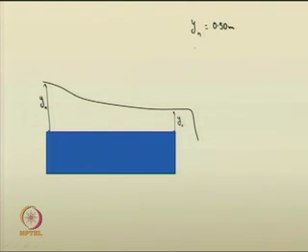Critical depth, you had evaluated the discharge; I am not going to compute it again. At that time, you had evaluated the discharge as 1.5203 meter cube per second. Subsequently, you evaluated the critical depth as 0.3891 meter.